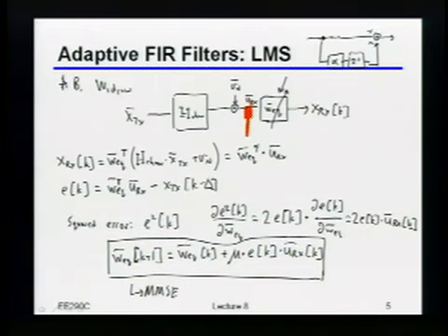XTX is the correct bit, but notice I'm never really using that explicitly, because I'm just looking at what's the analog input into the equalizer. That will be the combination of the actual thing I transmitted going through the channel with noise on it. That's what's going to show up at the input. So you're right, it does have XTX in it just because URX has XTX in it, but you can just think of it as the analog input into the equalizer. Does this make sense to people?